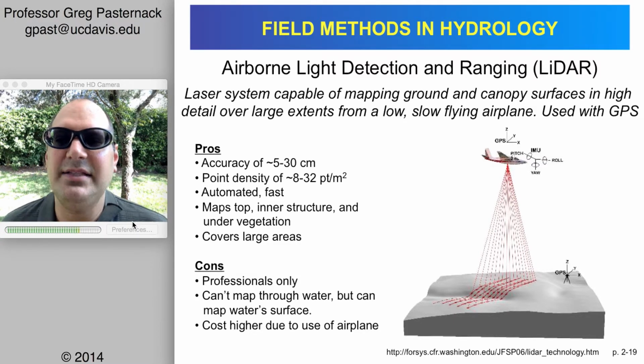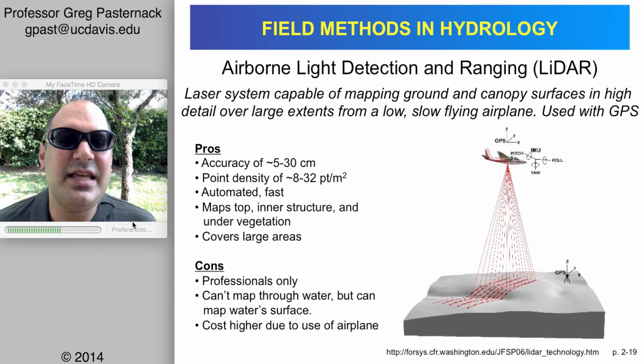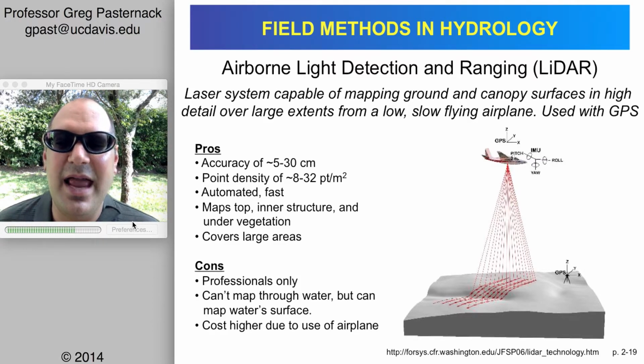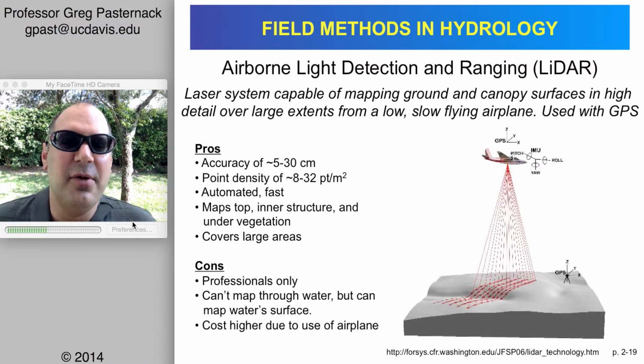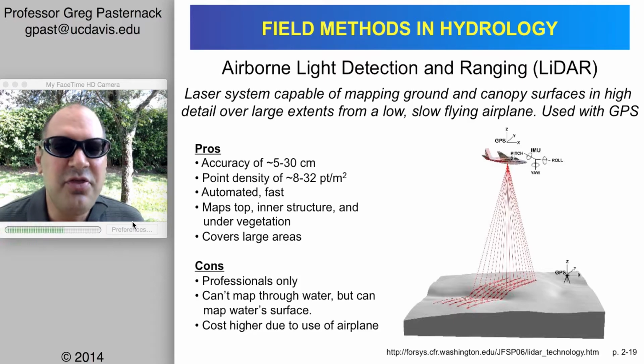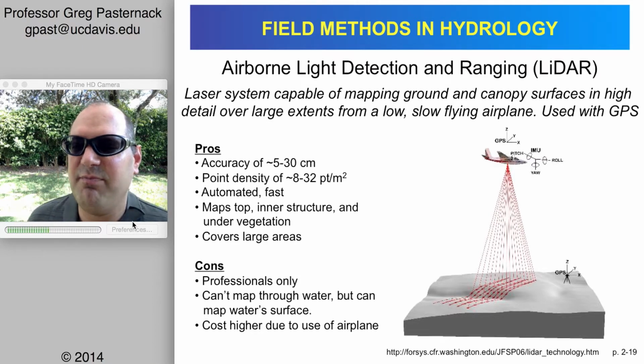The cost just depends on the size of the area, and the minimum cost is just an inescapable starting fee because you have to get the airplane to your location. You're basically having a pilot and a plane and a staff on site, so there's that cost. Once you're in an area, the more land you map, the more efficient it becomes, so the cost per point goes down. The other thing, when you map an area with LiDAR, you could be getting 100 million to 1 billion points. So then you have to be prepared to manage millions and millions of points, and that becomes an effort unto itself.